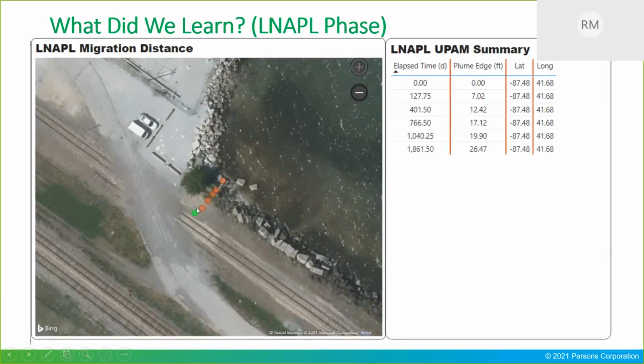So you're able to literally, just like Saroj showed for the dissolved phase, say that if my conditions don't change, if my transmissivity stays the same, my natural loss stays the same, my conditions do not change significantly, I can say that there is a risk of my plume migrating or at least getting close to the receptor in 26 years. To give you some context, that 112 feet that I showed you in the long time approximation is a little over 100 years, I think 150 or 200 years, before the plume actually reaches the receptor. But again, as you can see, it slows down, and this is where my plume is going to be at the end of the 5-year period, just to give you a visual context.